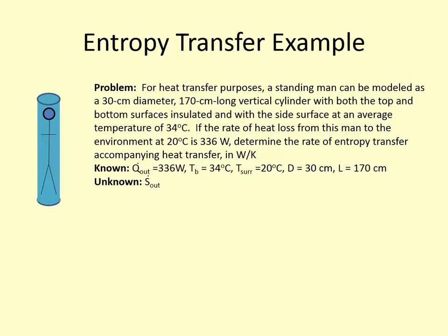Okay, so rate of entropy transfer. What do we know about entropy transfer? How is entropy transferred? Heat, by mass. Heat and mass. Okay, so do we have any information about this man's mass changing? Is he spitting or eating or something else? No, we don't have any mass transfer in this problem. So the only way that entropy can be transferred is via heat.